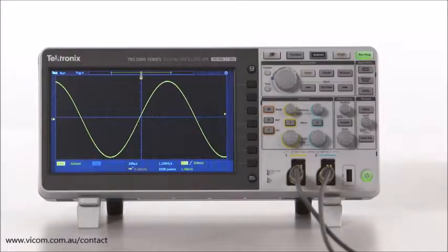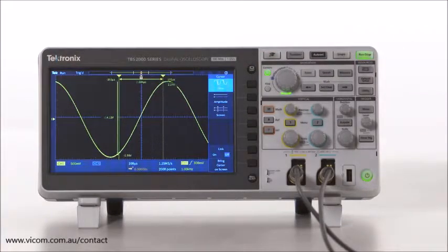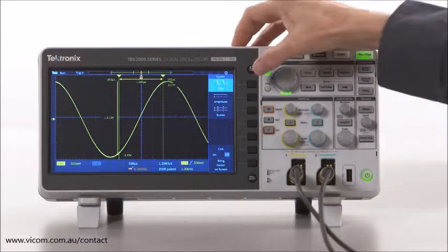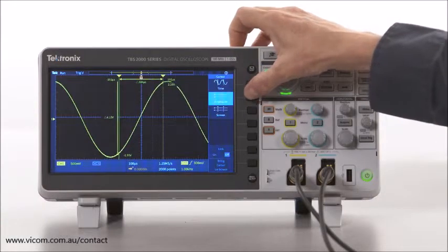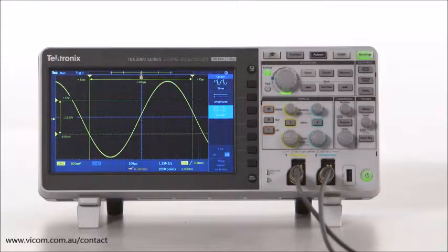Taking measurements by eye is quick, but it's not very accurate, and as you've seen, it requires doing a little bit of math. On-screen markers called cursors can help you make more accurate time and amplitude measurements. On this scope, you activate the cursors by pressing the cursor button. This scope has 3 types of cursors: time or vertical cursors, amplitude or horizontal cursors, and screen cursors, which is a combination of both horizontal and vertical cursors for time and amplitude measurements.